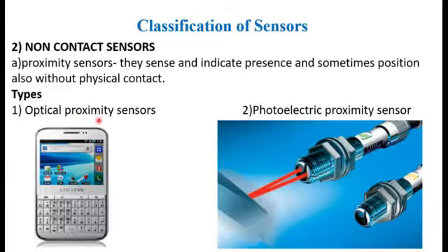These sensors detect objects directly in front of them by detecting the sensor's own transmitted light reflected back from the object surface. Here the sensor transmits some light, and whenever there is an object in front of it, the light is reflected back from that object and detected, which shows the physical presence of the component.